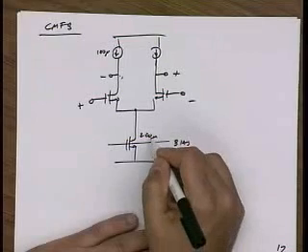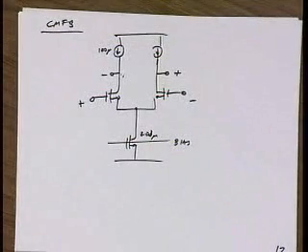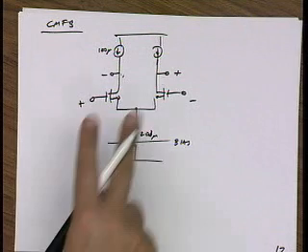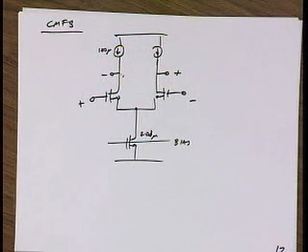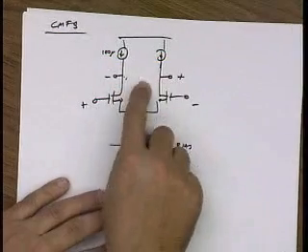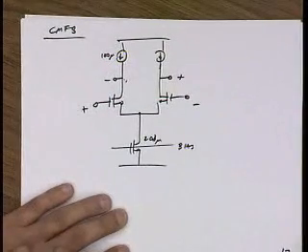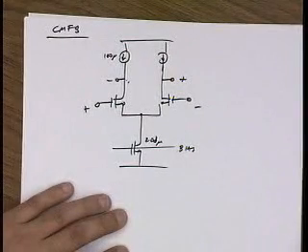So let's say instead of 200, this were 201. So what would happen to the circuit? Where would the common mode of the output be? Would it be plus or minus? Would it be VDD or VSS? VDD. You sure? Right, I'm pulling more current out of this node than I'm adding to it, right? So it would actually go to VSS, right?